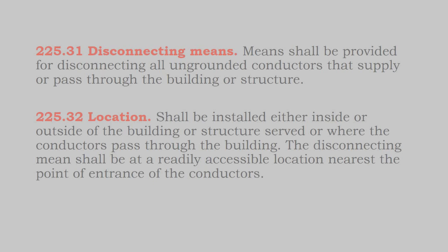So what we're talking about for this disconnecting means is really, the utility is looking at that knife switch disconnect on the edge of the building as the system disconnect, or the main solar array disconnect. The disconnect up on your rooftop in your rapid shutdown, that's considered an additional disconnect, and so the readily accessible requirement doesn't apply for whatever reason.